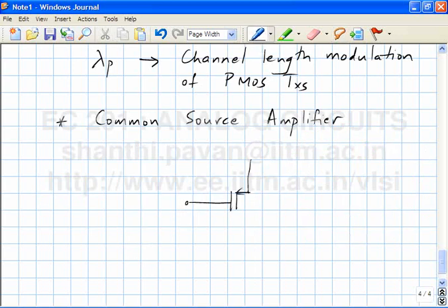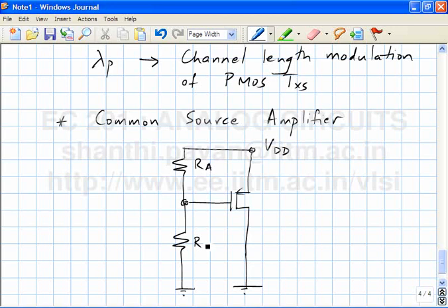We said it's kind of a terrible thing to waste a battery. So you can derive one battery from the other. And please realize that in the PMOS case, the source must be at the highest potential. Correct? So this is RA, this is RB. Let's add the load. The drain. Okay. What is the potential at this node? VDD times RB by RA plus RB.